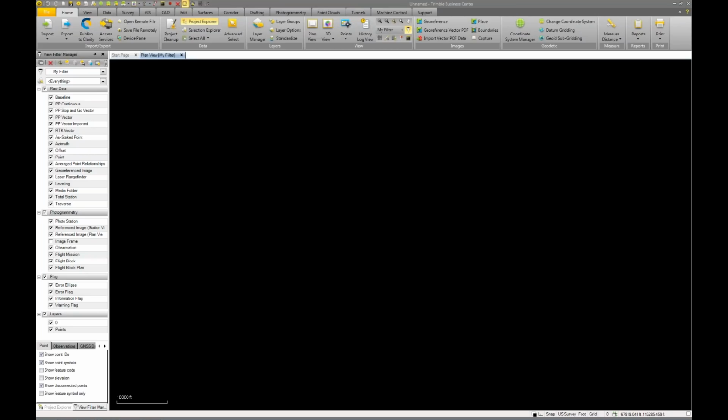Sure, thanks, Joe. And like you mentioned, Joe, that is one of the formats we use with our new designs that are in the Open Roads Corridor Modeler. Kicking out that ICM format and bringing in the Trimble Business Center as well, and that does work to bring that information over. So once we have that information assembled, we've got it put into a Trimble Road XML file. I'm going to switch over to Trimble Business Center here, and let's start looking at the data we've got.